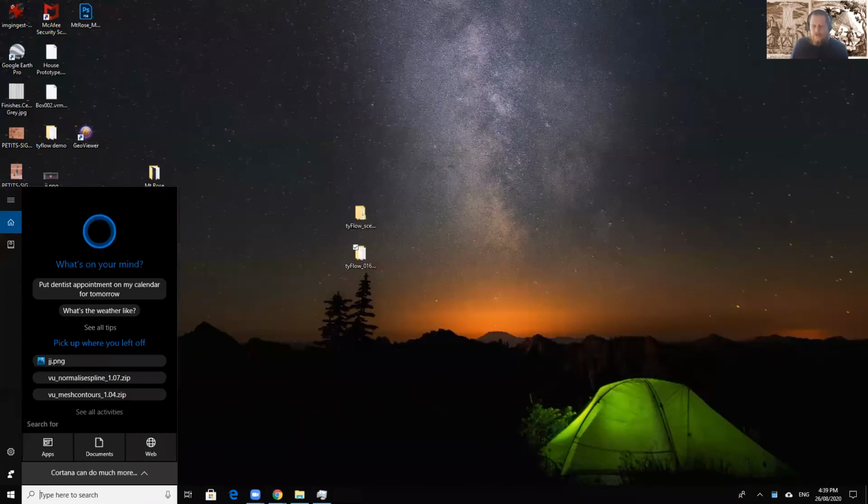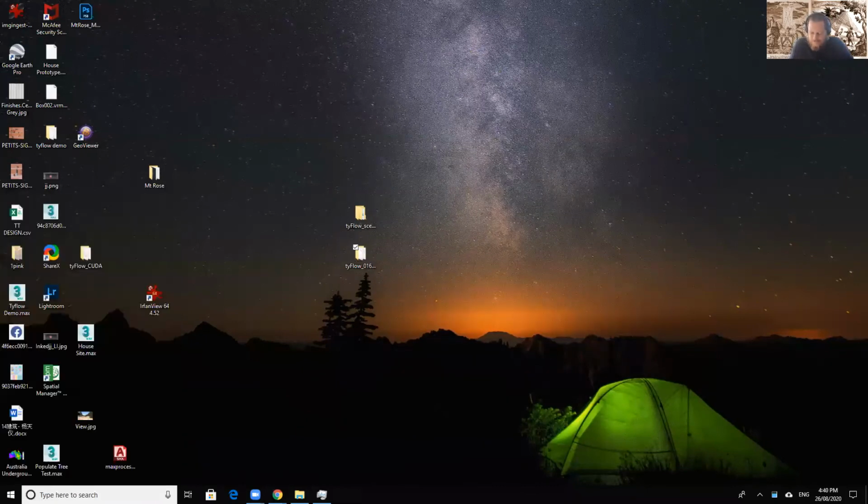It's probably a good time to point out that you should save regularly. Yeah, I did. I actually have to stop the share for now. It's worth pointing out that if the machine crashes and you haven't been diligent about hitting Control S every now and then, Max will do an autosave for you. You need to dig a little bit to find it, but I think it saves by default every 5 minutes, a version, and it just keeps writing over them. I think in the preferences you can set it to keep more than 3, which I like to set to 25 or something.